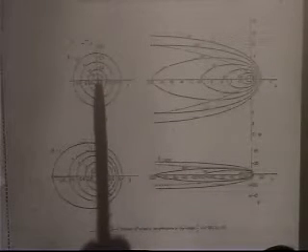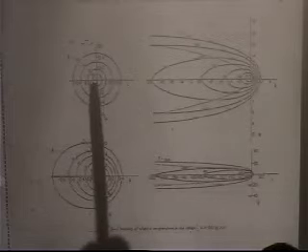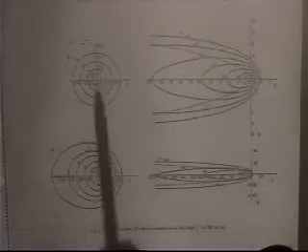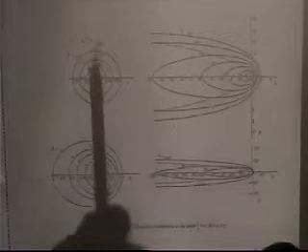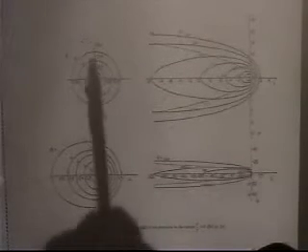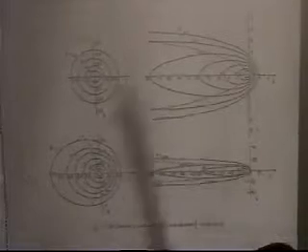Anyway, here's a very slow-moving heat source, and if this center circle is the weld pool, let's say that's the fusion line, you can see this little dot-dash line here is the locus of the maximum isotherms, the maximum distance they move out.